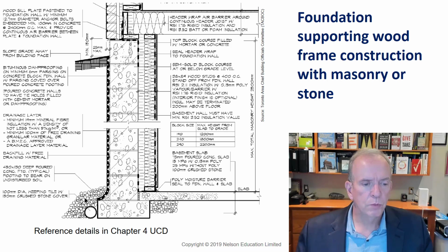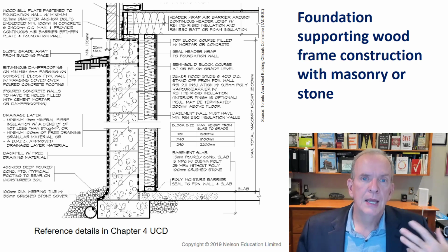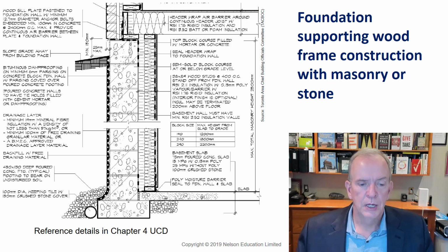We've got gravel placed over here, so if moisture goes down, and it will, the gravel helps the moisture to seep through over the weeping tile, and the weeping tile will take excess water away from the foundation and redirect it towards the storm sewers. It'll connect up to the storm sewers. So we also have a concrete slab in the basement, and we got gravel below.